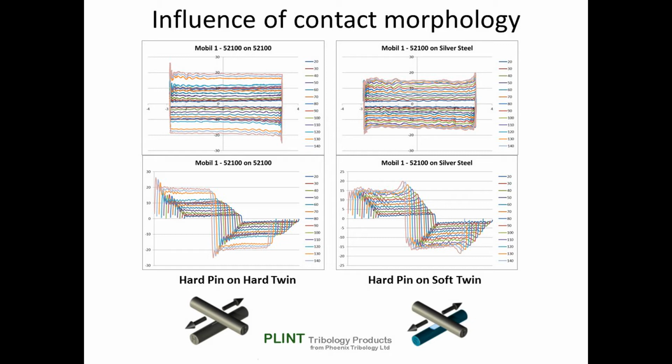The hard on hard specimens produce a well-defined spike and essentially square subsequent friction trace, indicating sliding over a flat, unworn surface. The hard on soft specimen does not start with a spike, but ends with the rise in friction. This is a result of the specimen wear and the deformation at the stroke ends. The moving specimen starts each stroke by sliding down a slope and ends each stroke by sliding up a slope.